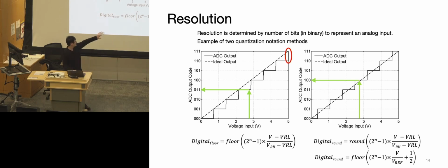So hopefully this will make the equation make a lot of sense. Basically, it's whatever the measured value is minus the low value of the reference, and then times that with the value of each step, and then they're going to be the floored version of this conversion table.